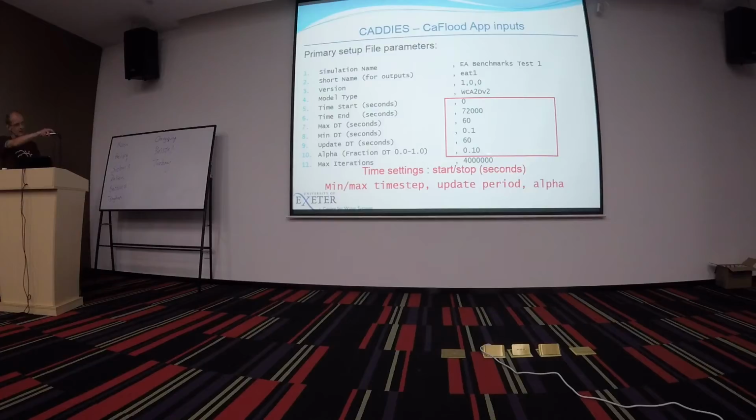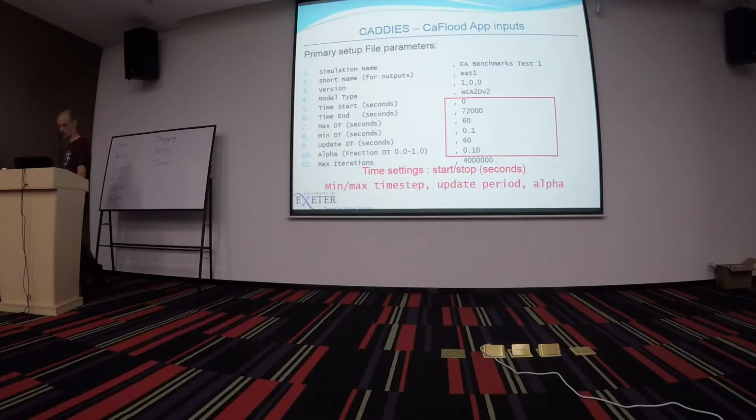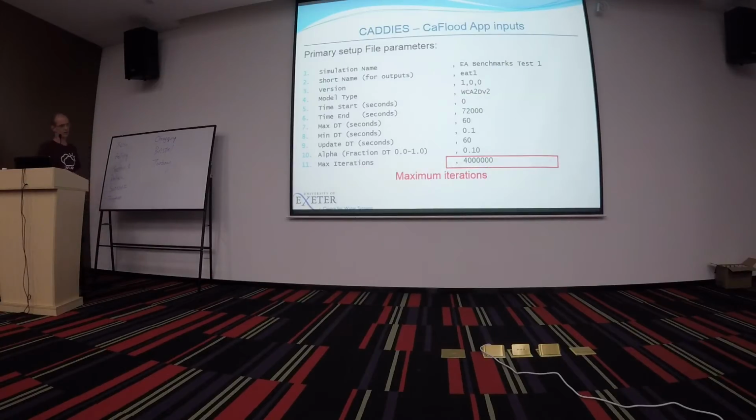And our relaxation parameter, if you have that at 1, it would use the fastest velocities. That might not be completely safe. You still need a way to automatically derive this. And the maximum number of iterations, effectively, you just want to have that as large enough to cover enough iterations to do the simulation.